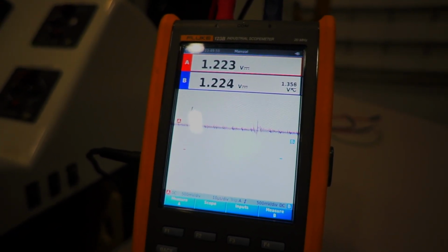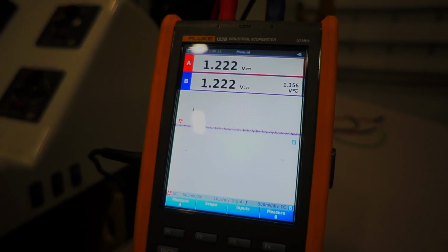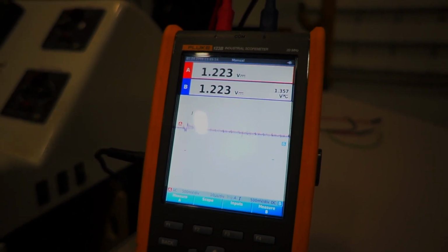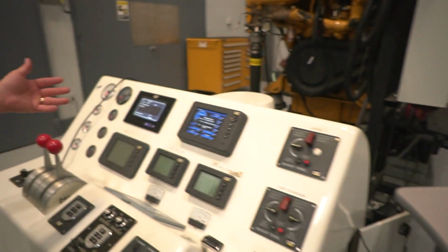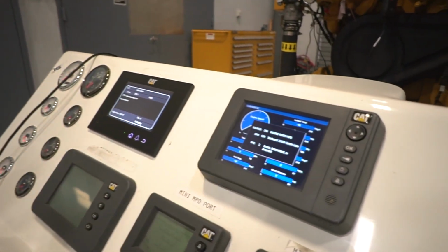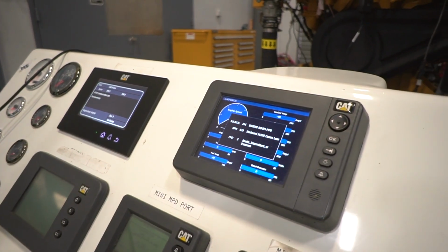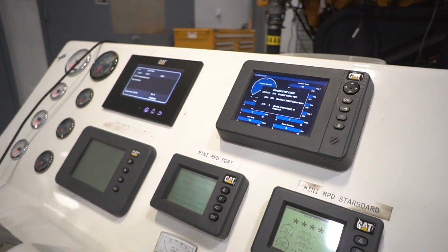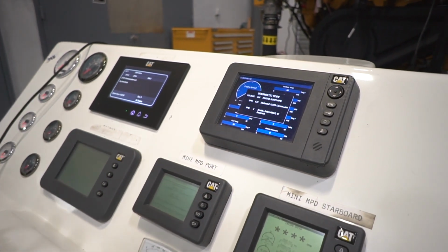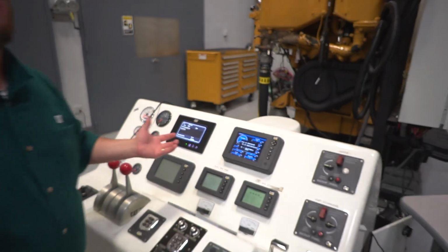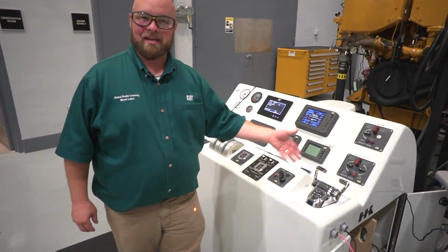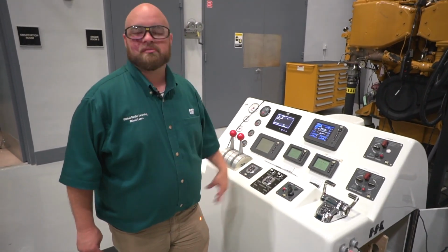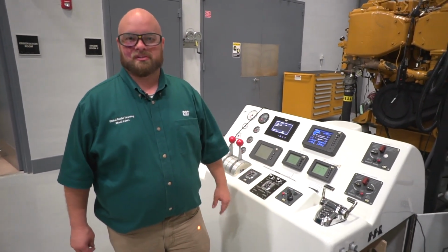So basically, the chip is just reading 1, 1, 1, 1, 1, 1, 1, 1, 1, 1 all the time because there's no differential voltage between the two. And when the panels and everybody that's asking for information sees that, hey, it's just reading a bunch of ones, there's no data, then obviously nobody's happy up here. So these panels are all looking for information. They're not getting it from the ECM because we have our CAN shorted and no information going across. We're getting all kinds of alarms here.